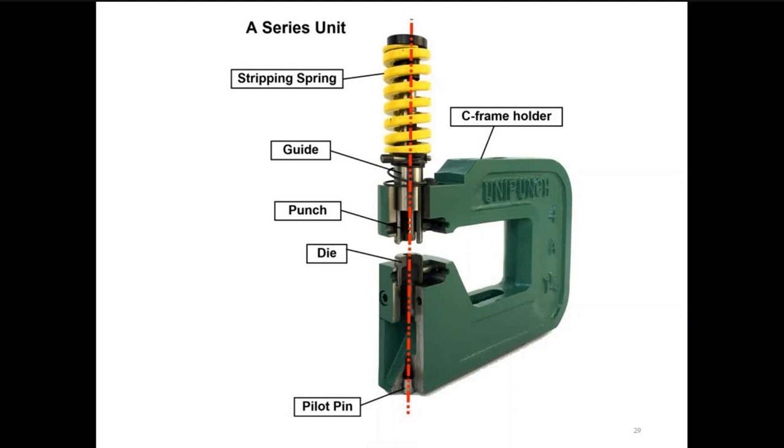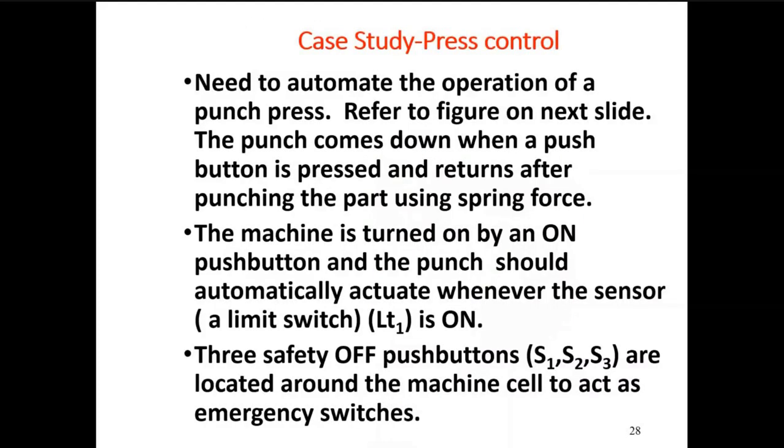So let's assume I want to automate this process. In the traditional way, this is how it is done. There's a die on a big machine which is already made and mounted onto the press. The operator is there in front of the machine. The machine could be 10 feet high, 20 feet high, depending on how powerful it is. So the operator manually loads a blank sheet, could be steel, aluminum, brass, whatever, and of different thickness. And then he adjusts the pressure. If he's mass producing, the pressure will stay adjusted to the desired force that it has to generate.